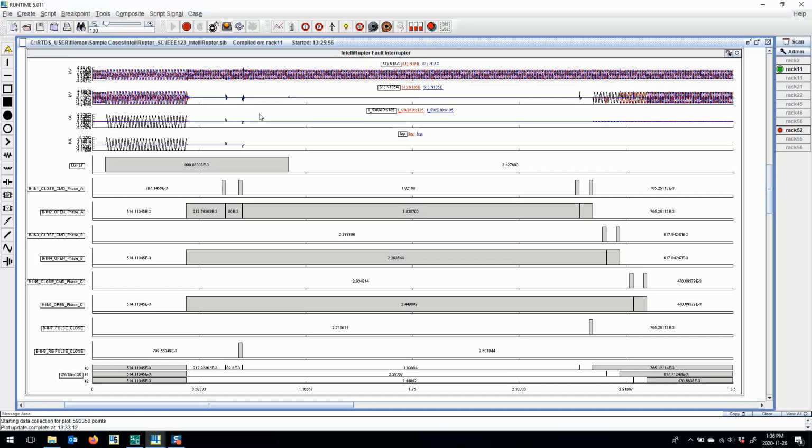Okay, now next we can see our test 1 occurs here. Our fault duration here is 1 second, so at this point here the fault elapsed and the fault is no longer present. Now 1.8 seconds after test number 1, test number 2 should occur. So let's have a look at the results, the pulse closing from test number 2.